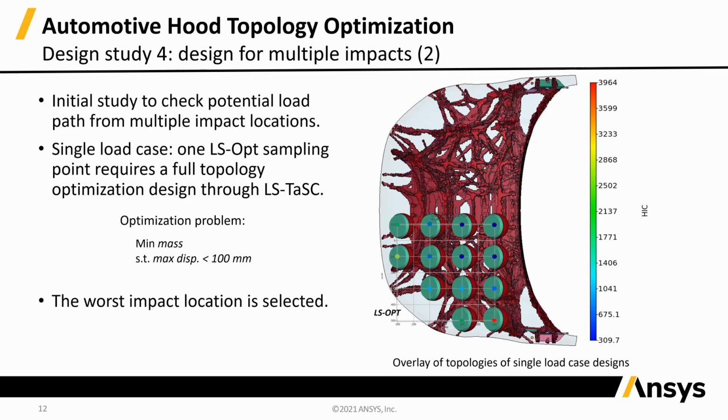Okay, so this is how we're going to do the worst case design. What we're going to do in the worst case design is find one load case such that if we design for that load case, all of the other load cases are satisfied. If we can find such one load case, then we only have to design for that one. But the problem now becomes finding that load case. That's what we're doing in this slide.